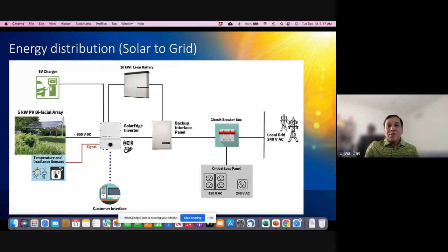If you can connect PV with just an inverter to a local grid, that's how the US is doing for almost all rooftop solar. It has only three things: a PV panel and a solar inverter, and that connects to the local grid. So the only maintenance cost is the inverter, and inverter technology is improving very rapidly. I'm not sure how long the new inverter lasts, but old technology, like 20 years old inverter technology, used to last for 10 to 15 years. So you have to replace that. What that means is you have to replace that inverter every 10 to 15 years.